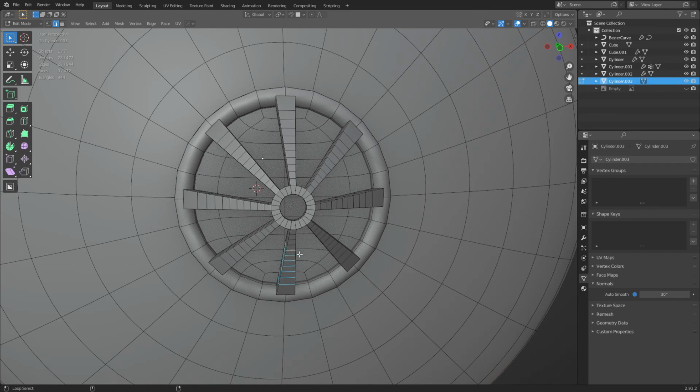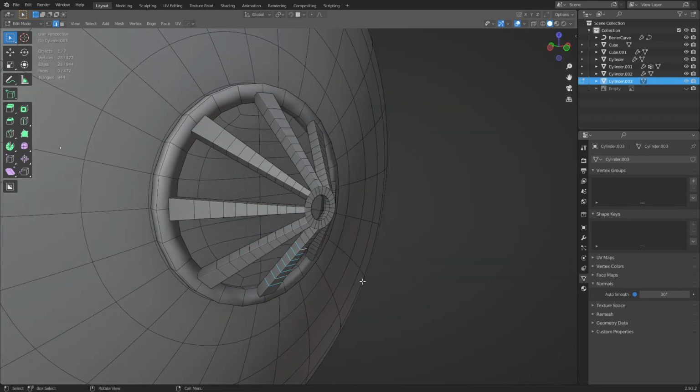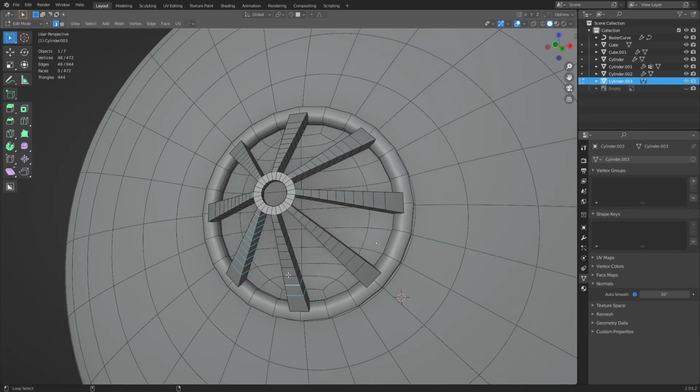Things like this. Press Shift G, select faces by length, see what we can, oop, maybe not. These kind of things, you know, just go through and optimize out. You don't need all these faces. Even if this was a game model or a bake model, I doubt you're going to bake a ton of detail into this area.